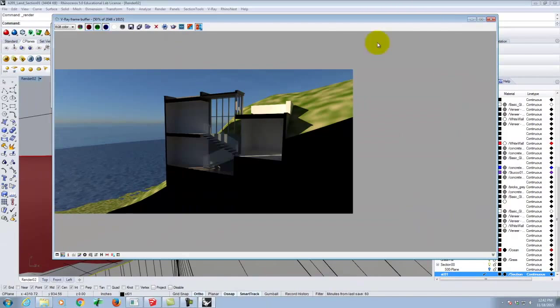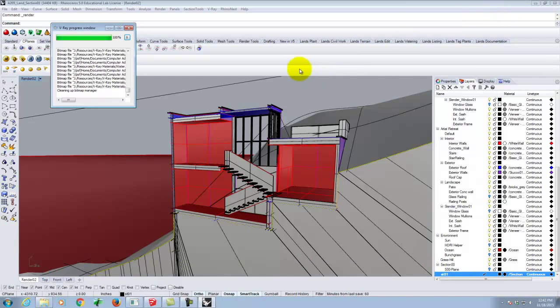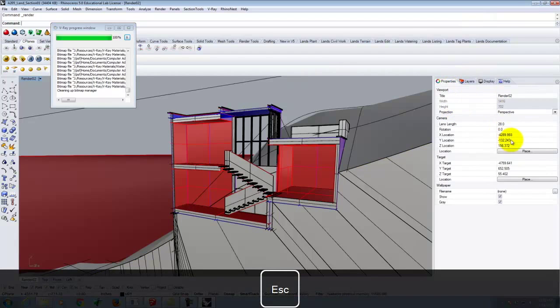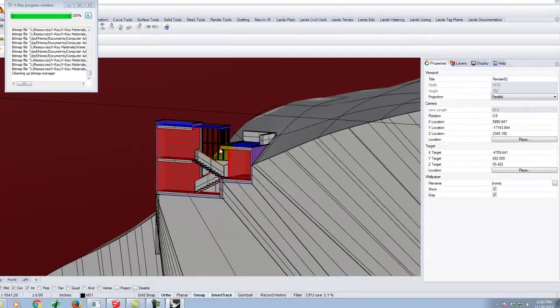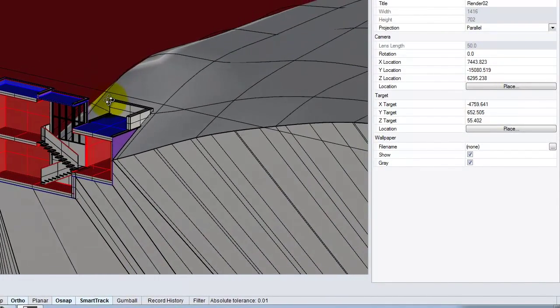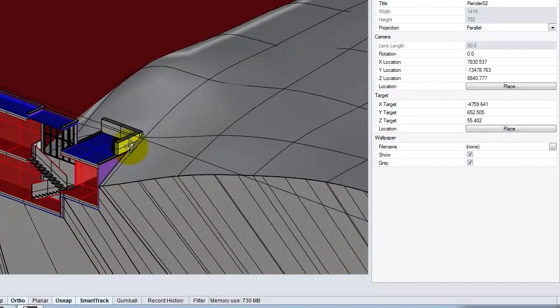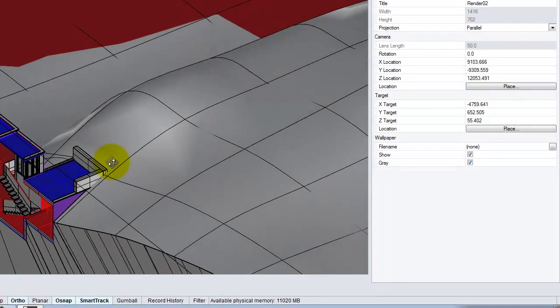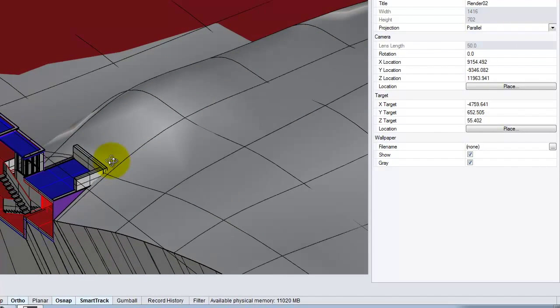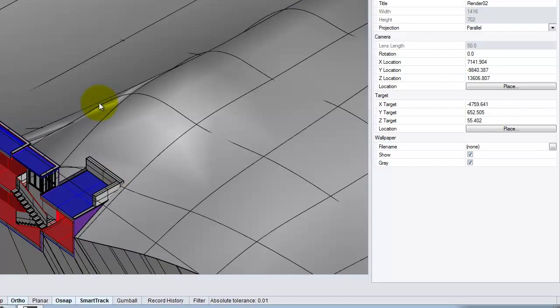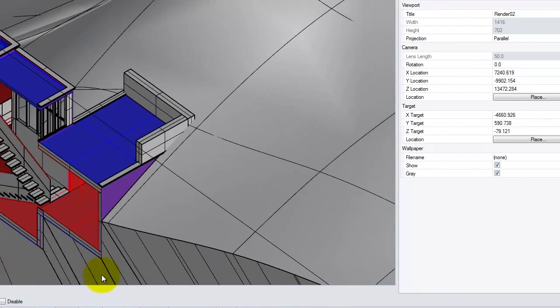If you were not interested in the sectional perspective and instead wanted more of an axonometric, remember we can switch the properties here from being in perspective to parallel, which is going to switch it into more of the traditional axon look. And you could do it as the 30-60 or the 30-30, depending on where you wanted it. You could also do it as an approximation of a more of a 45 or a 30-30, something like that, depending on what view you wanted of it.